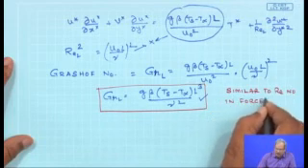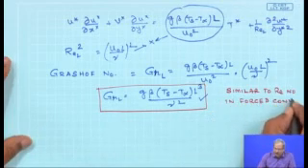So, the same role the Reynolds number played in forced convection, where we know that the Nusselt number is a function of Reynolds number and Prandtl number, the same role will be played by the Grashof number in the case of natural convection or free convection. The value of the Grashof number can simply be expressed as